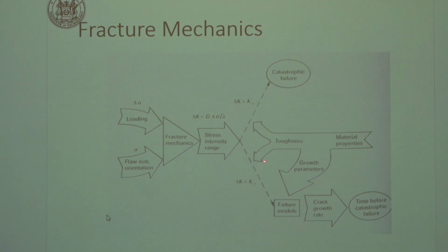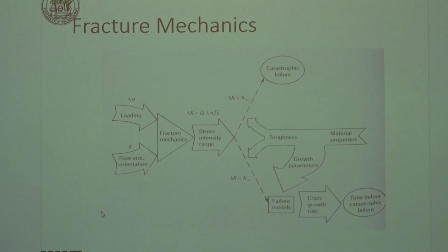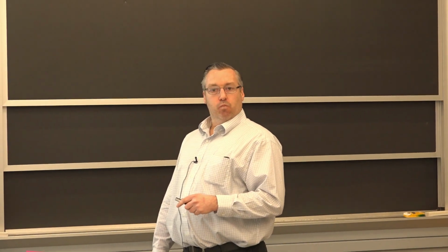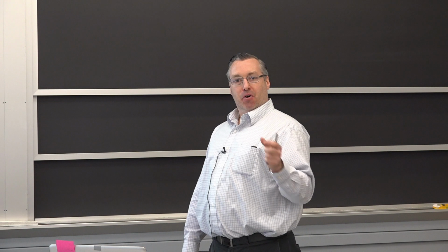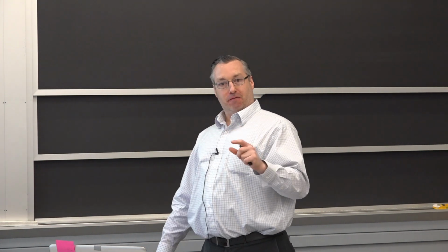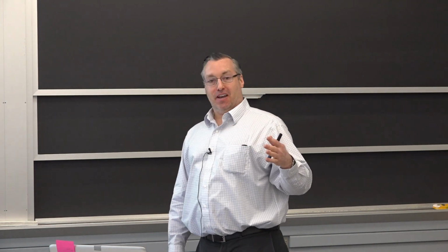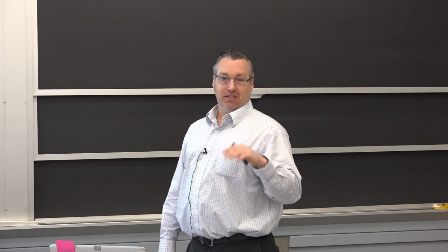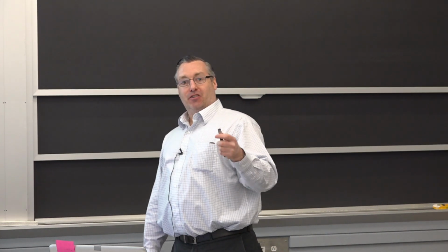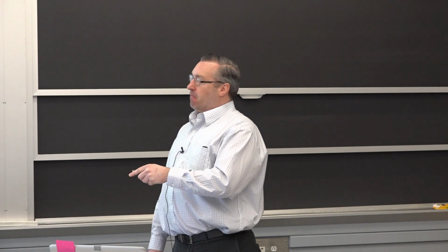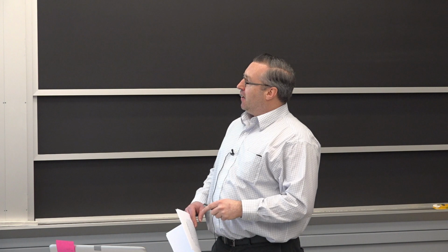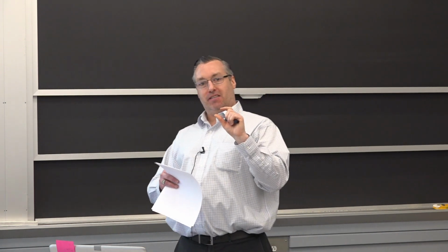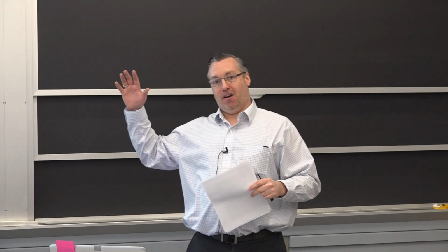That's quite a low fracture toughness, and when you see rail fractures, one of the things you often ask is, why hasn't AASHTO or other agencies put a minimum requirement in for fracture toughness? The simple answer is costs. It will cost the steel companies more to comply with a minimum fracture toughness of 25 foot-pounds or something like that. Right now, when you do Charpy tests, you see 3 and 4 foot-pounds as the value.